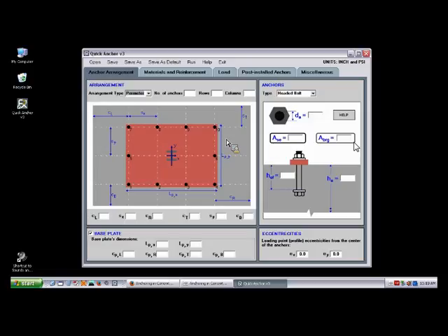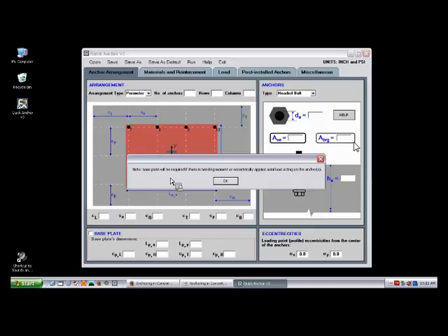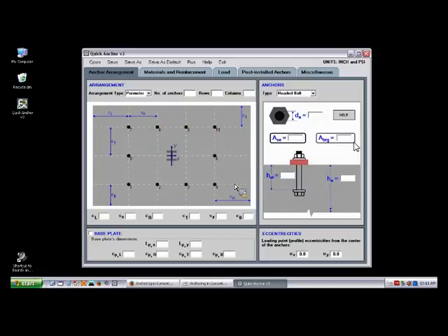And so if you do not have a bending moment, and when I say bending moment, it could be a directly applied bending moment about x-axis or y-axis, or it could be a tension with an eccentricity, which would also cause a bending moment, a net bending moment about the centroid of the anchors. So if you do not have any of those, then you could very safely uncheck this box at the bottom of the screen next to the text base plate, and you will see this message pop up that the base plate will be required if there is a bending moment or eccentrically applied axial load acting on the anchors. But if you don't have any of those, switch it off. Base plate is not necessary at all, and the base plate also goes away from this figure.